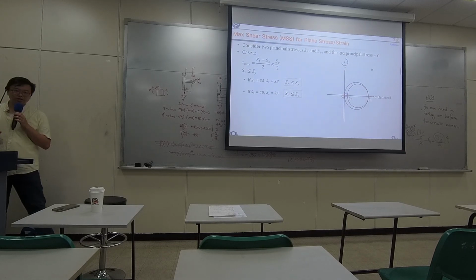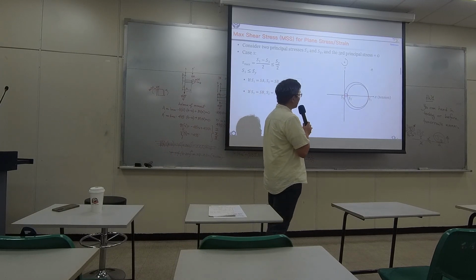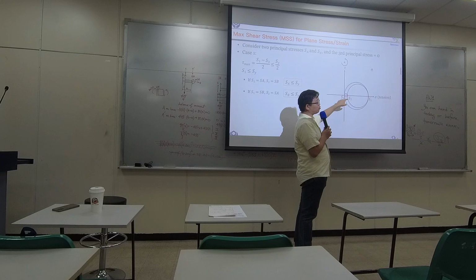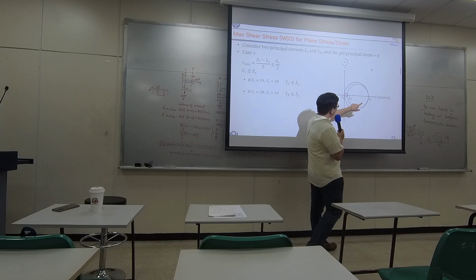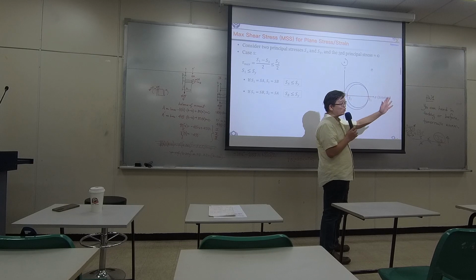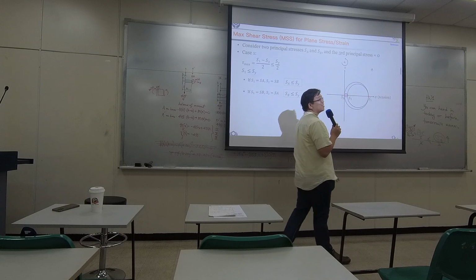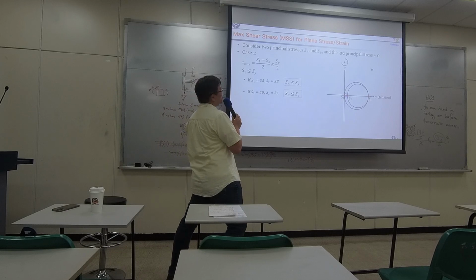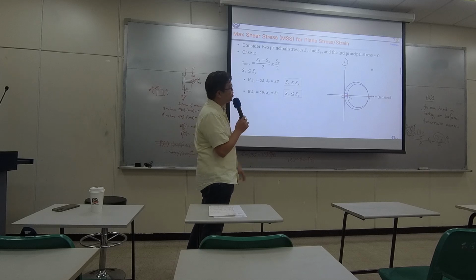Here's another situation. When we have first and second principal stresses positive, and our third principal stress remains 0. In that particular case, the maximum shear doesn't lie on the Mohr circle along the 1 and 2 planes. The maximum shear goes on the other plane. Okay? That's why we need to do this discussion, because there are situations like this.